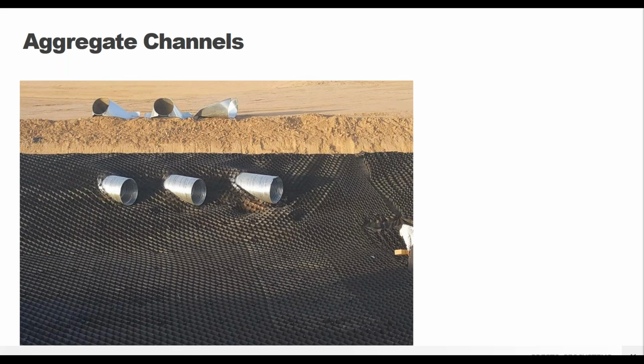And the area right below the drainage weirs should be built up more robustly. This is going to be an area with the highest potential for stone washout, because you're going to have turbulence coming out of those pipes. It's also where the flow is going to potentially be the highest. So definitely consult your hydraulic engineer to find where those areas of concern are, and we can adjust the GEOWEB system to make sure those areas are fully protected.